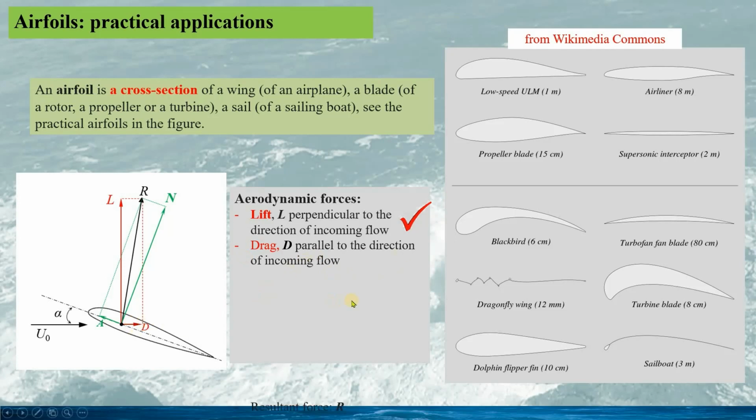See here. This lift and drag form a resultant force R, shown here. Another important aspect for the airfoil is the aerodynamic center. For most practical airfoils, the aerodynamic center is at the quarter of the chord. We will consider this in this talk as well.